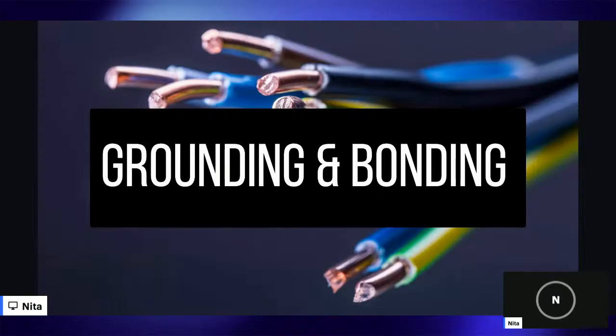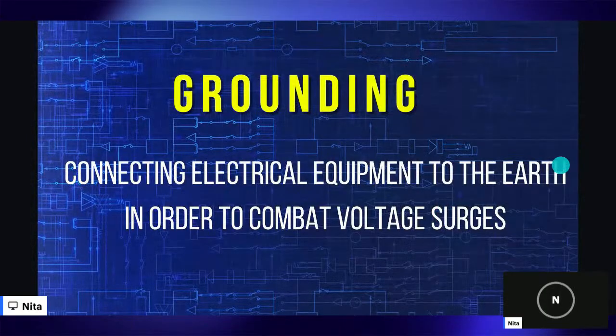Okay, so let's start with grounding. Again, we are not just sticking a wire into the ground. We are building a complete path for our electricity or our current to safely return to its source if we have a fault or a problem. We ground to protect people and our equipment.